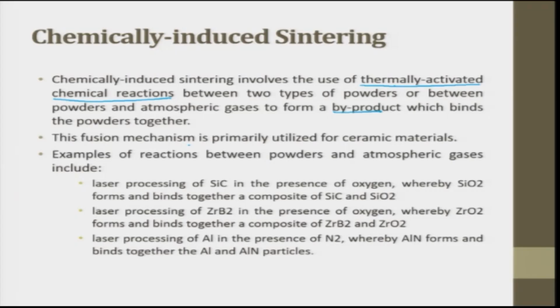This fusion mechanism is primarily utilized for ceramic materials only. An example of reaction between powder and the atmospheric gas is laser processing of SiC in the presence of oxygen, where SiO2 is formed and binds together the composite of SiC and SiO2.